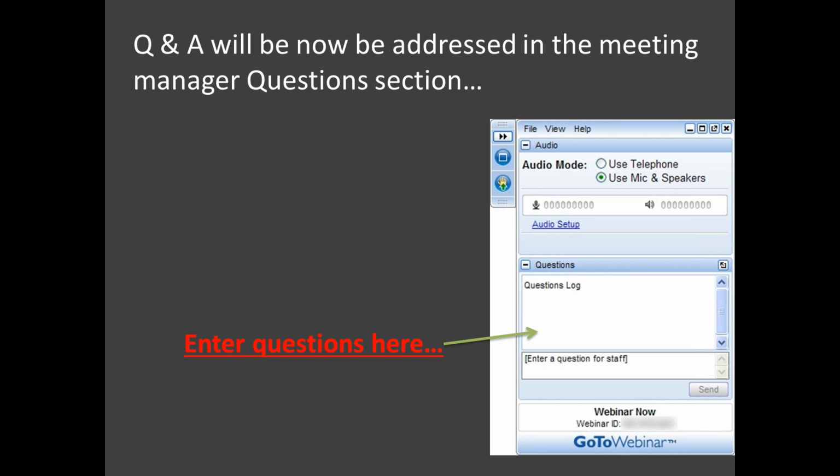Yeah, we have a lot of customers that will use that. If they have a machined component, instead of having a rough cut drawing print, they'll just say, here's my machined dimension, my overall. I need a bar stock that is that value plus whatever machining tolerance you want. If it's a 1/4 inch, 1/2 inch, whatever, they'll add that to the overall length and just route it up to the next incremental stock. We have some customers, this is incredibly impressive. It takes a little bit of setup on the front end, but the amount of time it saves you in the long run is phenomenal.